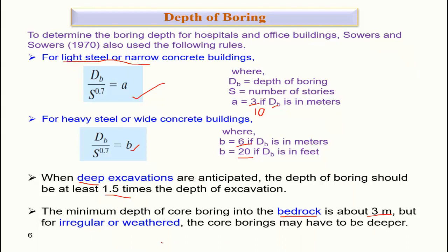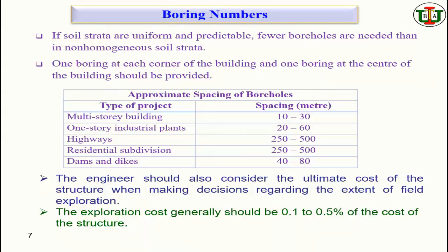But if you find the bedrock has some problem, or it is weathered bedrock, not permanent bedrock from molten magma or other formations, you might have some cracks or some issues with the rocks. At that time you can go for more depth of boring until you find a satisfactory result.